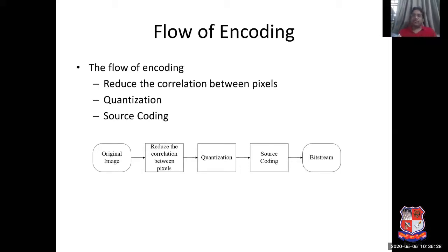If you round it off to 2 or 1, then at the receiver side, if you get 2, you cannot say whether it was 1.5, 1.4, 2.2 or 2.1. So once the quantization is done, it is an irreversible process and it is impossible to reconstruct the original data. Quantization ensures that the process is completely irreversible, which means it is a lossy compression.